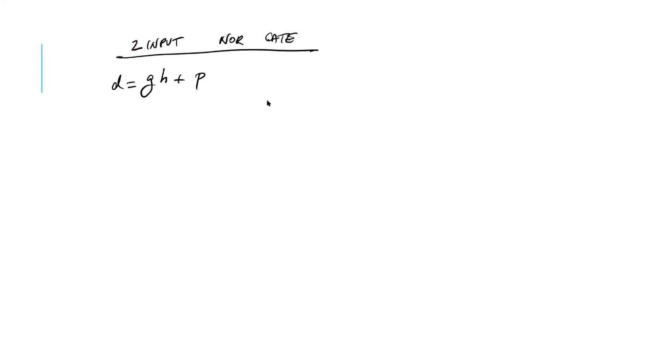Okay, so let's take a crack at it. Let's first draw the NOR gate. A NOR gate will have two PMOSFETs in series on top and two NMOSFETs in parallel. Again, we're comparing this to a minimum size inverter that has 1x and 2x size.